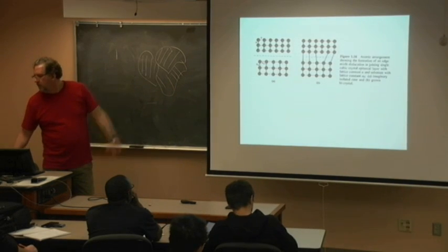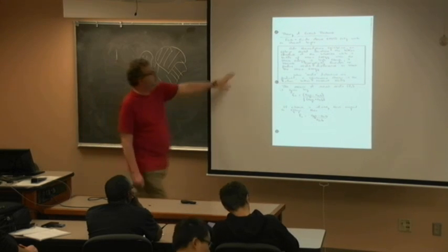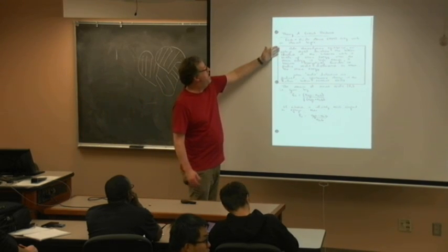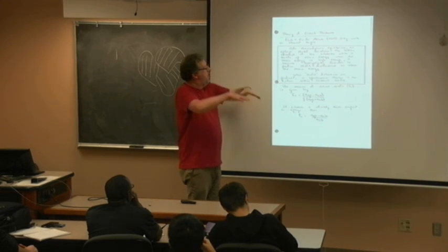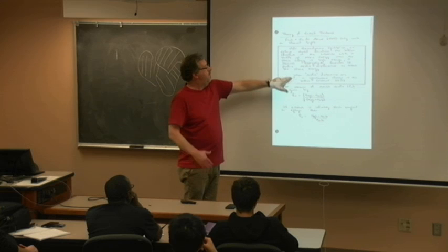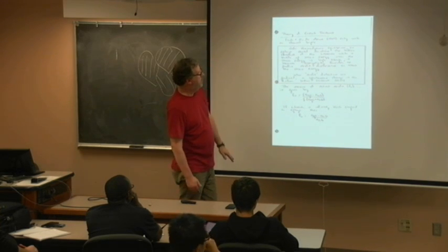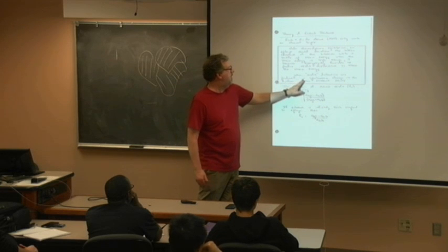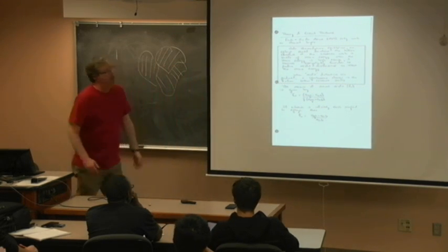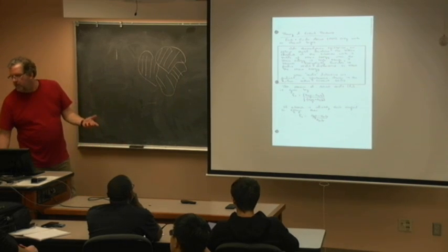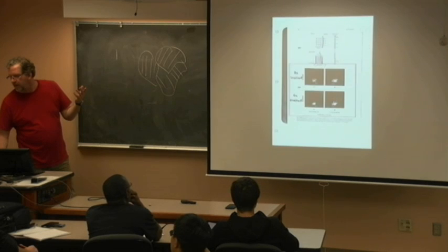Okay, so same thing there. Under thermodynamic equilibrium, the upper layer should maintain the lattice constant of the substrate while it builds up strain energy as it gets taller. When the strain energy is high enough, it becomes energetically favorable to, boom, make a misfit dislocation and release. So when misfits are produced, a spontaneous change occurs in the surface lattice constant. And you don't have to know my PhD. I know my PhD, but you end up with.